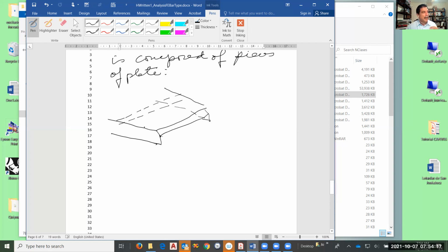There. And now we are considering that each one of these is a piece of plate. Of course, this model is much more complex. Immediately you ask, is the thickness uniform? You know that the thickness is not uniform, but we can assume that, for example, on the deck, on the side, and the transfer reinforcements, each one of these plates has uniform thickness. That's a simplification.